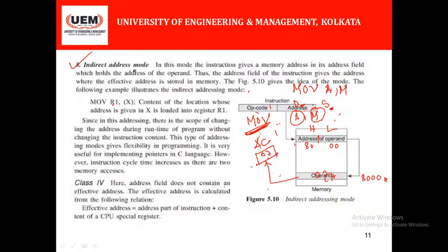So in memory indirect addressing mode, the memory address is not directly specified in the definition of the instruction. Rather, it is indirectly specified. Look at that, here the memory address is indirectly specified by a capital M variable, and capital M denotes the HL register pair, and the HL register pair holds the original memory address. If we go to the original memory address, we will find the data.